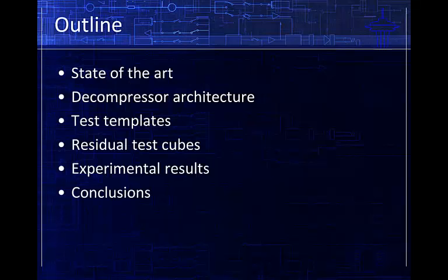In my presentation, I'll briefly review the state of the art. Then I'll present a new low-power decompressor with a template register. I'll introduce the concepts of templates and residual test cubes, which are fundamental to understanding of this method. Templates are derived from residual test cubes and communicate between the decompressor and ATPG to generate low toggle patterns that are easier to encode. We'll show experimental results and conclude.